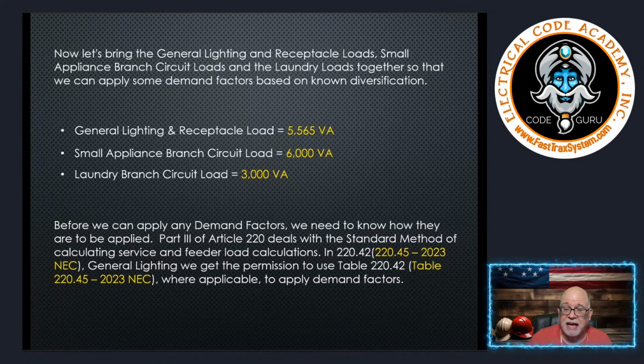Now, whether you use it or not, it's totally up to you. But you have to have the laundry circuit in using the standard method for that calculation. Because the code tells me I do. Now, again, if it's a multifamily building that has a laundry facility on site, then you have some allowances to not put the laundry receptacle in because it's available to all the tenants or all the people at the complex, and there's a separate laundry facility.